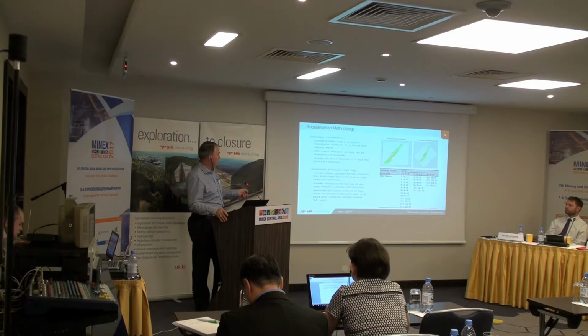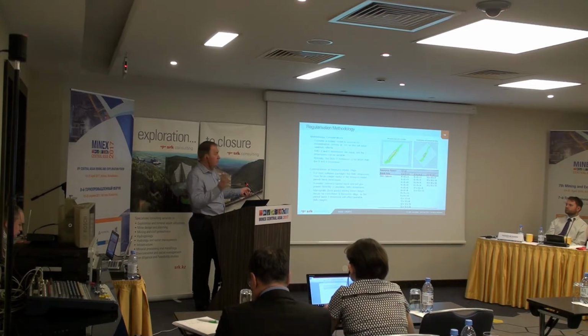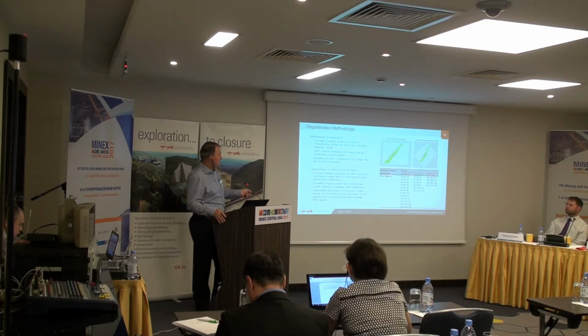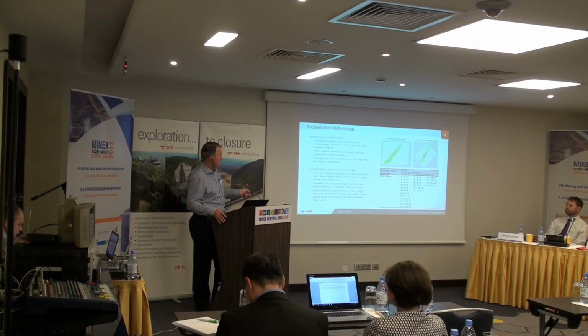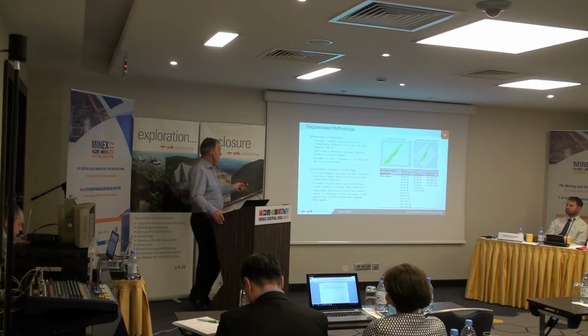What I was talking about earlier, the orientation of the ore body: if it's close to around 45 degrees, instead of what I would call orthogonal across the page, then you might consider rotating your model. Otherwise, you tend to have this sawtooth effect on the edge. When regularisation is undertaken, very often, though not always, your X and Y dimensions are the same, and the Z dimension is variable.